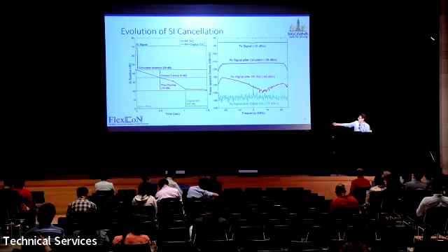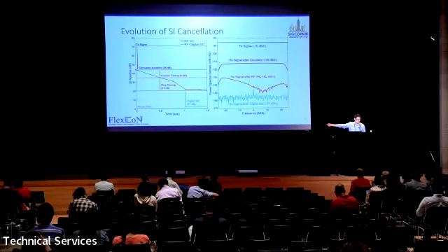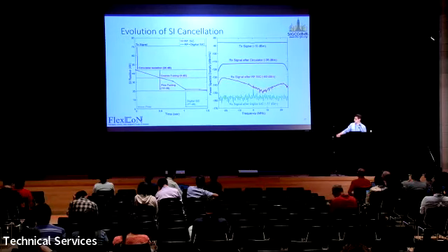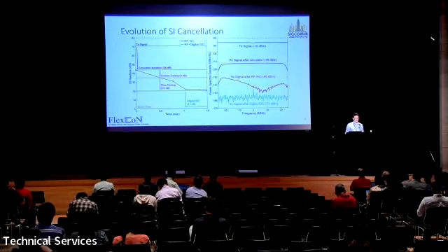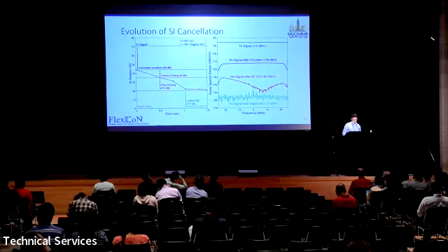In terms of performance, we have convergence to the optimal RF SIC state within 2 optimization stages. The circulator gives us initially 26 dB of cancellation. After convergence, the RF SIC gives us another 24, and then digital SIC brings it down another 17 dB to reach that noise floor number of -77 dBm. And again, this all occurs in real time. I'm sorry the video couldn't play. We can show it to you afterwards, but this all happens in real time. With every single packet that comes in, you get an improved RF SIC configuration.